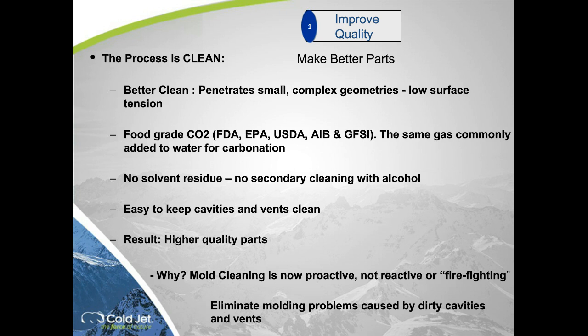Some people in medical molding are still using chemicals which may have kerosene as a base cleaner, and when you get done, you're either going to have to throw away the next handful of molded parts, if you're molding parts, or you're going to have to follow that clean with a secondary clean, cleaning with alcohol. If you clean the first time, you'll get a better clean, and there will be no secondary waste, nothing to cross-contaminate the next molded part. It will keep all your cavities and vents clean.